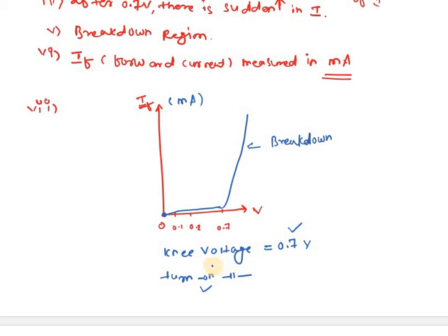Okay guys, so I hope you understood the basics of forward bias PN junction type. Now we'll go on to see the current equation of forward bias PN junction diode. So the forward current, typical formula I am writing it here. Forward current equation is given as IF is equal to I naught into e raised to V divided by eta Vt, minus 1.